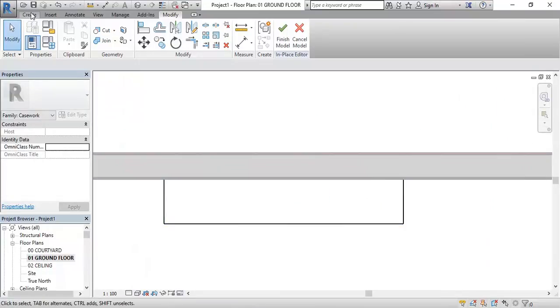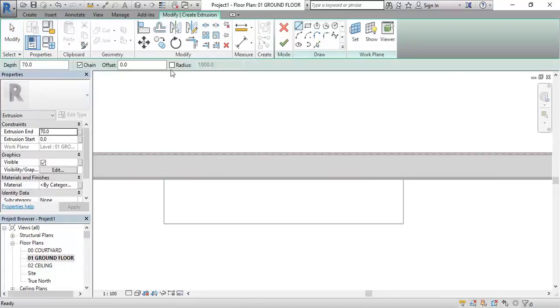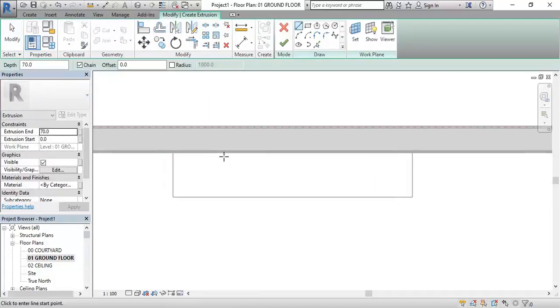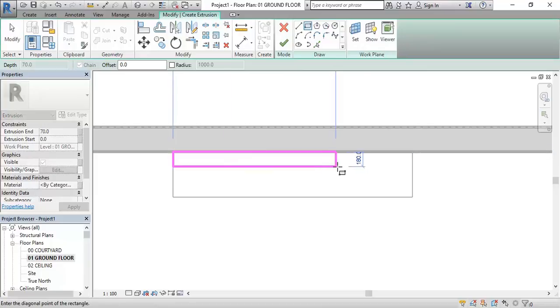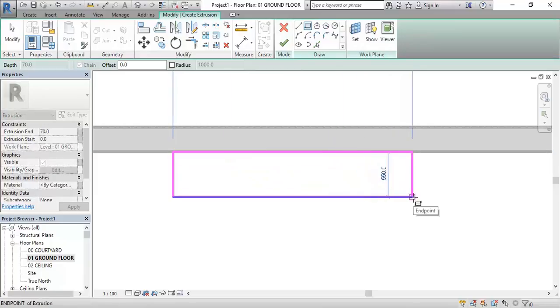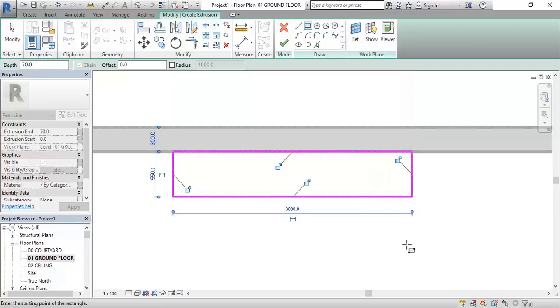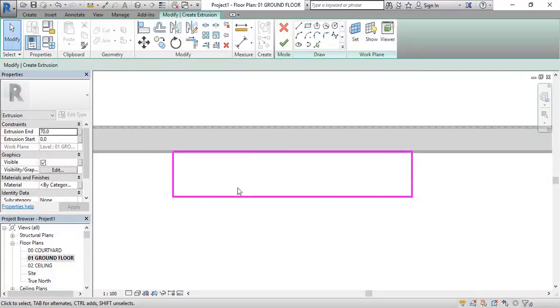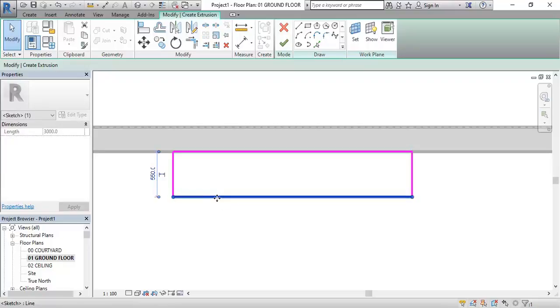plan, back to extrusion, and I'll just do a rough outline, and we'll add in the detail later, I think. So I'm going to make another, also use the rectangle tool again. Just going to click and snap to points on top of what I've made already. But then I'm going to select this line afterwards, and I'll just bring that out to 600 for now.